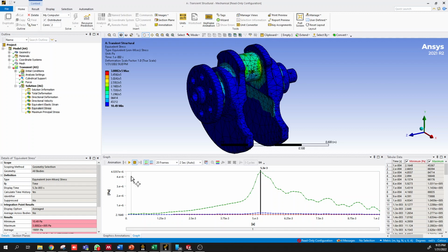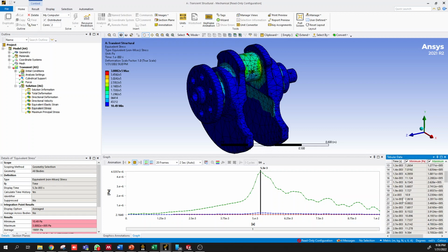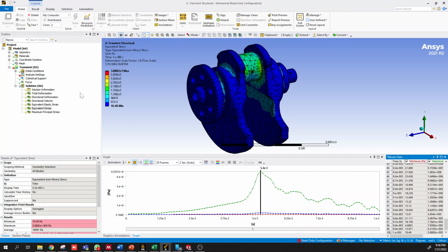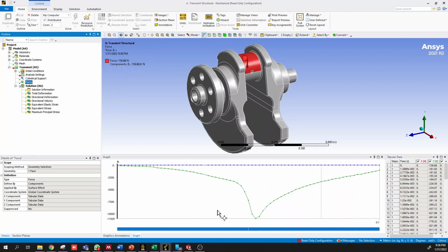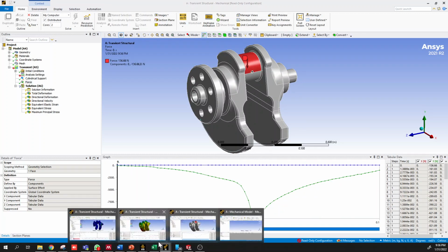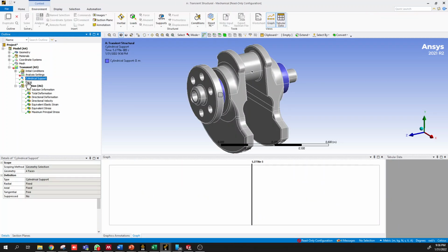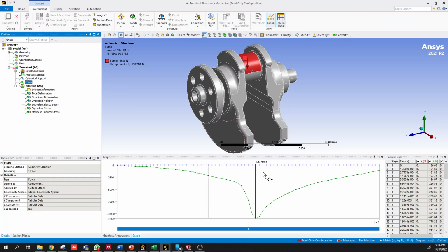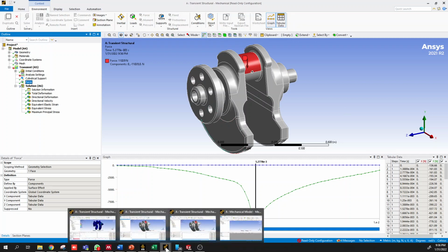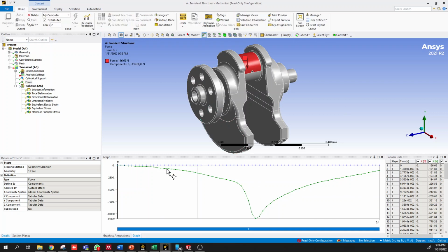slow engine speed where we're only operating at 100 times per second. If we do 1,000 times per second, let's say 6,000 RPM, now our load signal will go between 0 and 0.1, where this one was 0 and 0.001. So 10 times difference. So 1e-2 versus 0.1 as the load signal. Exactly the same load signal, we've just exaggerated the time scale.